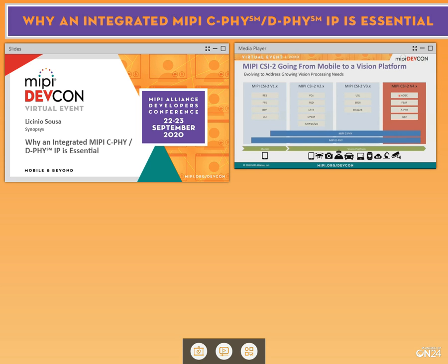There's this interesting use case, always-on sentinel control. The interest of having this is for some applications, for some use cases that require some always-on capabilities, using a low bandwidth, low power link that is always active. And if the application sees something that is relevant, it can switch to a C-PHY, D-PHY link. So this is also an interesting capability that is coming soon. And then obviously for me, there's additional capabilities being added for content protection and security.